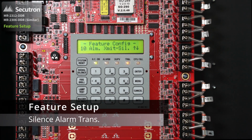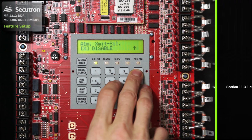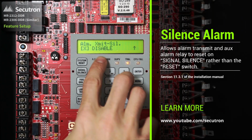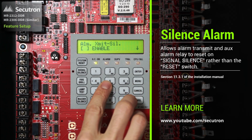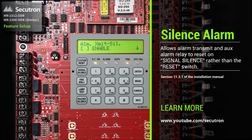The next feature is the silence alarm transmit. With this feature, if we press enter, by default, it has been disabled. We can enable it by pressing the up and the left or right cursor to apply the X. We use this function to allow the alarm transmit and auxiliary alarm relay to reset on signal silence rather than reset.